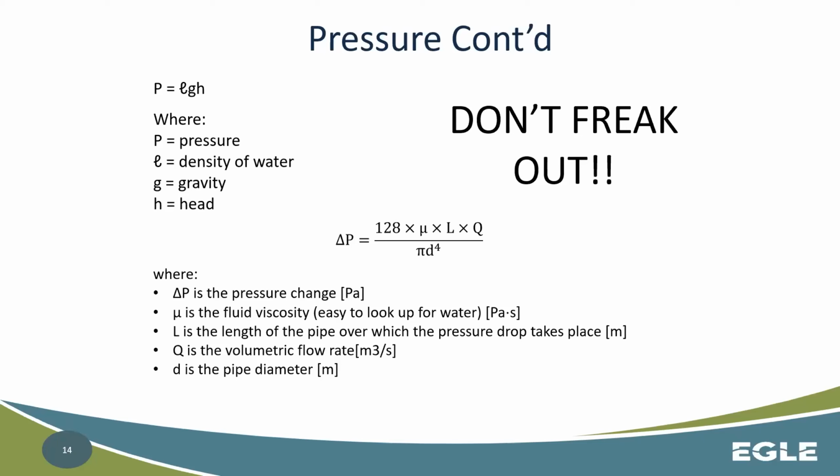So through this exercise, we could start to understand what is going to happen with our pressure if we start changing some of these variables. So using this equation, we know our constant variables. We know the viscosity, we know the flow rate, we have the area, so we can actually calculate the pressure change we're going to lose across a certain pipe length, right?